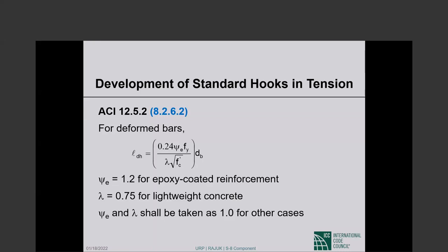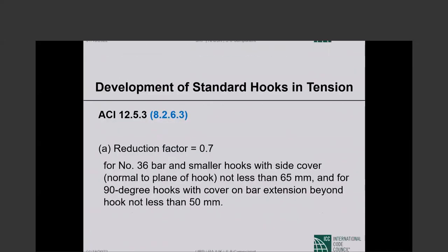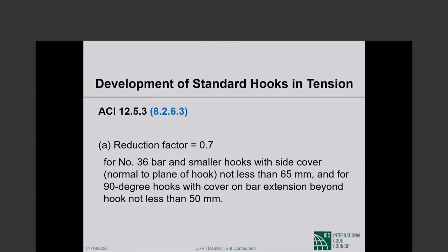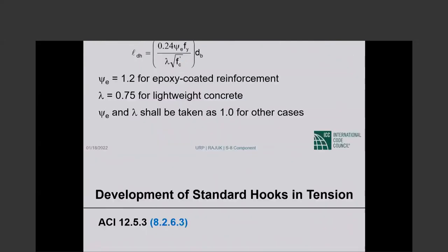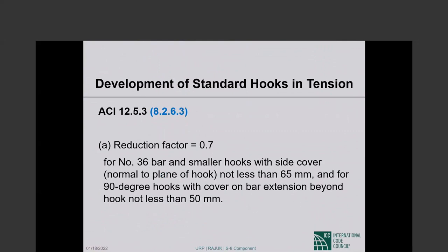Psi sub e and lambda shall be taken as 1.0 for other cases, meaning if you don't have epoxy coating, psi sub e is 1, and if you don't have lightweight concrete, lambda is 1. So that is the expression. Now there are reduction factors that are allowed.